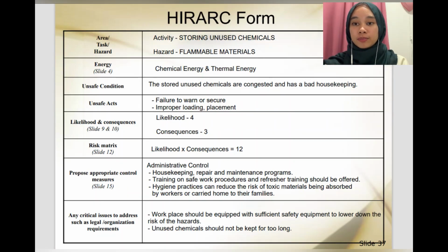Moving on to the HIRARC form, the working activity in this incident is storing unused chemicals. The hazard in this incident is categorized as flammable materials because the chemicals that were stored can explode upon reaction to the surroundings. The two types of energy involved are thermal energy and chemical energy. The unsafe condition is that the stored unused chemicals are congested and there is bad housekeeping, which leads to the explosion. Meanwhile, the unsafe acts are failure to warn or secure. Secondly is improper loading or placement.